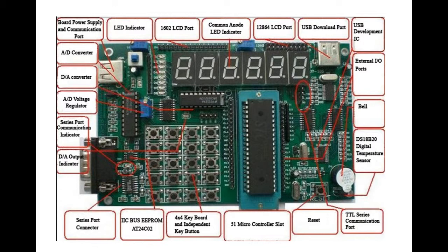In that situation, we need the EEPROM to save the relevant variable information. That EEPROM is a product of the company Philips, so that's the reason why it uses this sort of communication method. It's called I2C bus based communication. I will introduce more details about that when we get to that test, which is in lesson 10. Alright, pretty much that's the test.